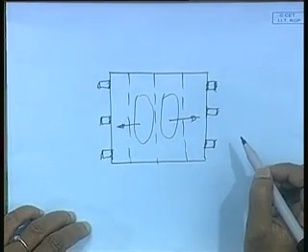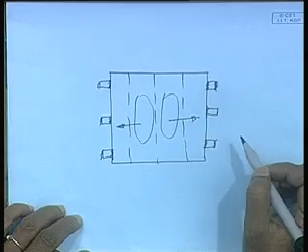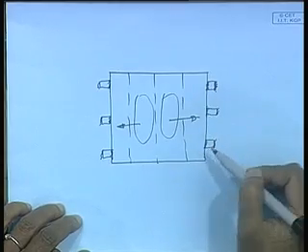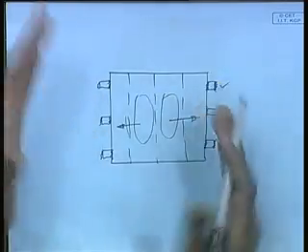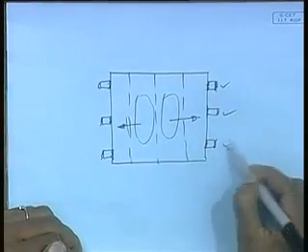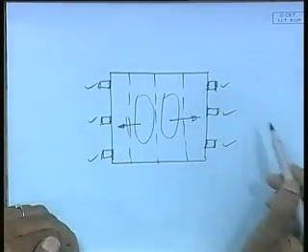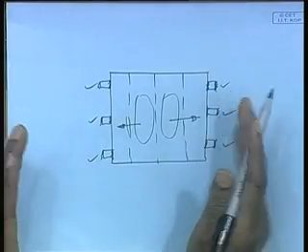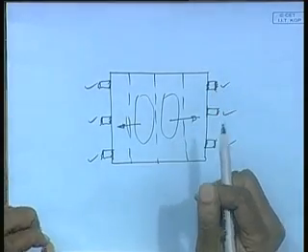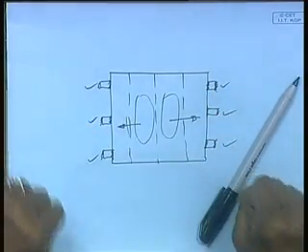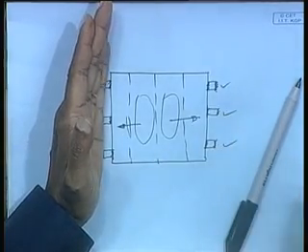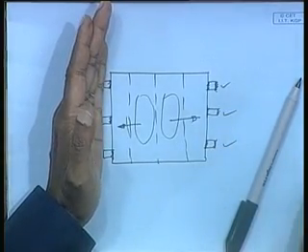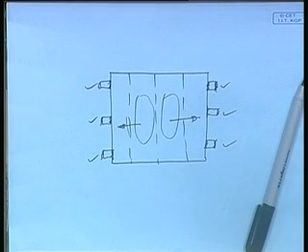So, this is a very simple technique, but it has to be done in a proper logical fashion, depending on the size of the structure, the number of lugs, the dimension of the lugs: welded, heat it up and then weld it. When it cools down, it automatically puts the plate in tension. So, one side I weld first, the other side I only heat up and weld, right. So, these are the distortion mitigation techniques.